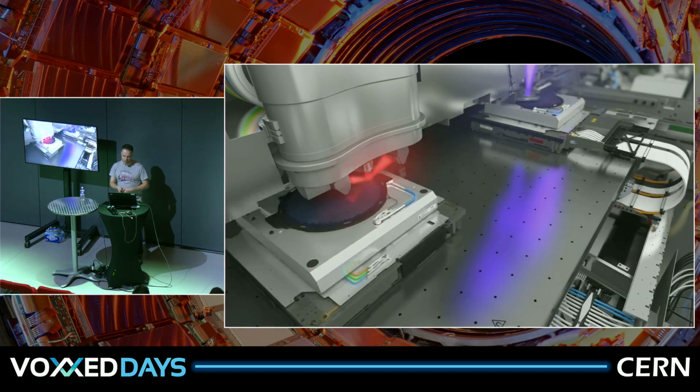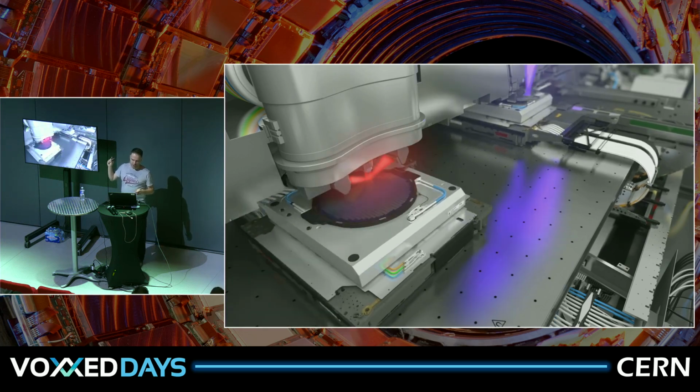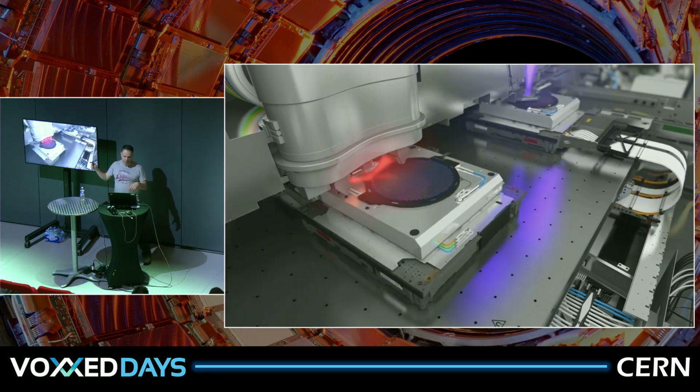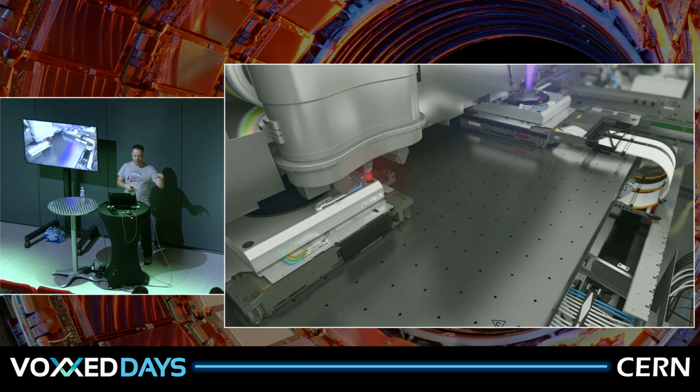And then it looks like this. So on the right, you see the patterns being printed. On the left, you see that the wafer is analyzed. So it's sort of pre-calibrated, and then it goes to the right table to be printed. And they do that basically to save time. Now they can do the pre-calibration at the same time that another wafer is being printed, and while the wafer is being printed, they do extra calibration stuff. So it's basically parallelism, what we're doing here.